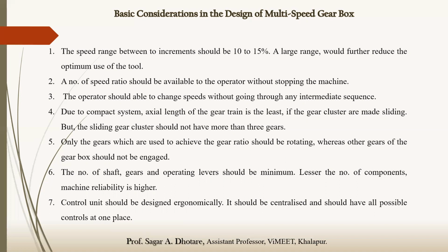Due to the compact system, the axial length of the gear train is least if the gear clusters are made sliding ones, but the sliding gear clusters should not have more than 3 gears.